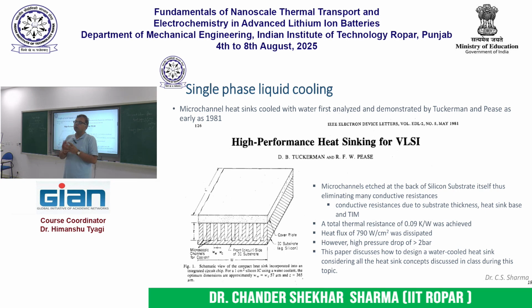So how to maximize the heat flux while staying in laminar flow? You would know that for laminar flow in a closed duct, the Nusselt number is a constant. That is, it is not a function of the Reynolds number. So whatever flow rate is there, as long as you are in laminar flow, the Nusselt number will stay constant, okay.